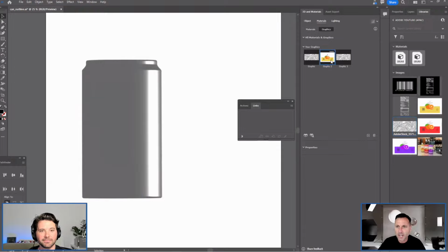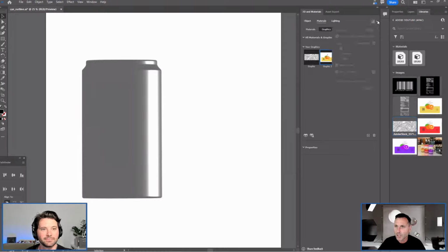Once you've got that, you can obviously just click on the image that you want to use, and then be able to map that. If I double click on that, sorry, that should just then map straight onto my object. So I'm just going to close. I think that's still loading, and making sure that that's not there. Your graphics, your materials, got that, your graphics, and you should be able to just drag and drop that straight onto, maybe I've got to have my model. Sorry, yeah, you've got to have your model selected. Yeah, and then click on it.